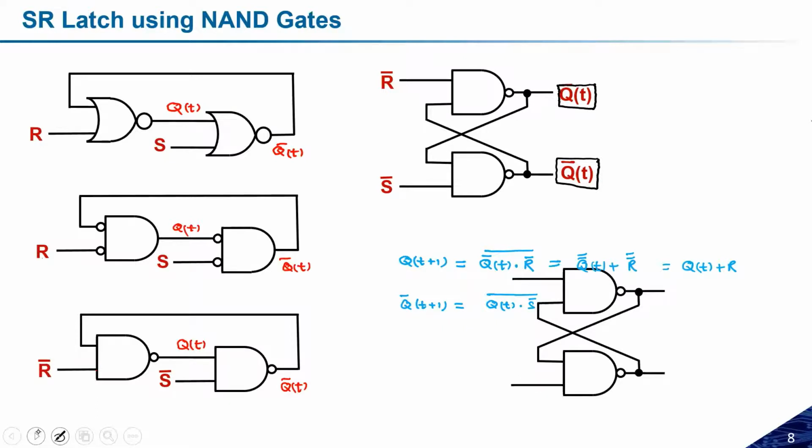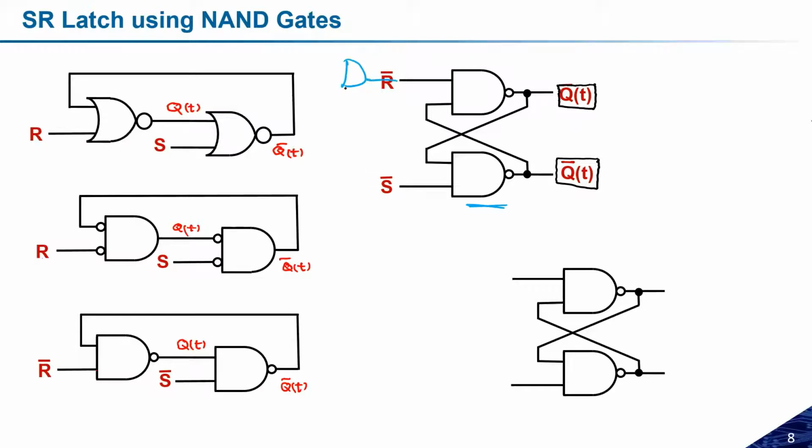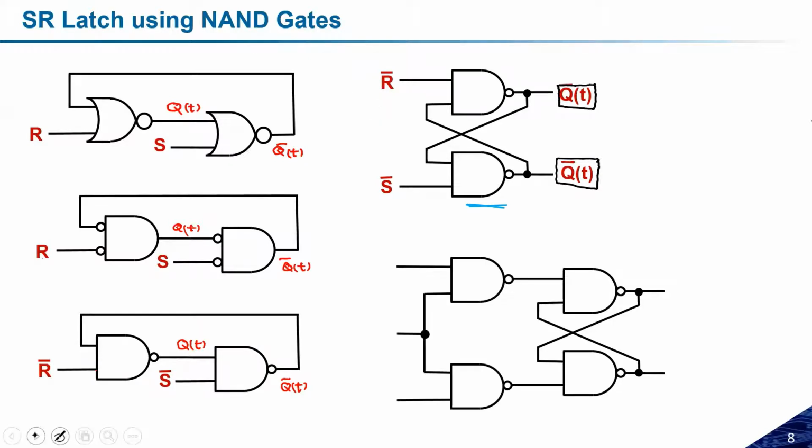I think I need to write it properly. Because I have already written the next circuit, you can check it out. Suppose I want to make this latch clock controlled. We know that if we connect AND gates to the inputs, and one of the inputs is controlled by the clock, then it becomes clock controlled, or a gated latch. To make it a latch, I can use this NAND gate.